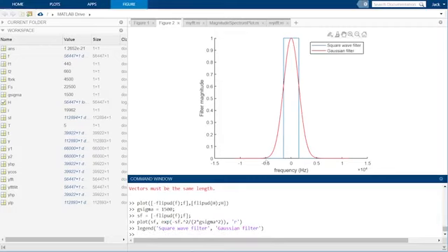So the Gaussian shape, the normal distribution bell curve, is unmistakable. The so-called bell curve has a maximum height of 1 where f is equal to 0, then smoothly decreases towards 0 as we move away from the 0 frequency. The point of steepest descent is where f is equal to sigma, which in this case is 1500. This is why we choose the sigma for the Gaussian as our cutoff frequency. Using this smoothly sloping frequency suppression function as opposed to the square wave filter can often produce better results with fewer artifacts. Okay, let's try it out.